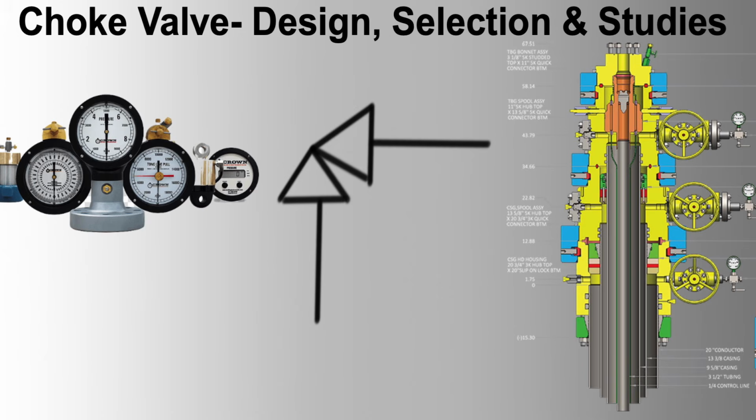2. Flow characteristics. Linear: flow rate changes linearly with valve position. Equal percentage: flow rate changes exponentially, suitable for applications with significant pressure variations. Quick opening provides maximum flow rate quickly, useful for emergency shutoff situations.